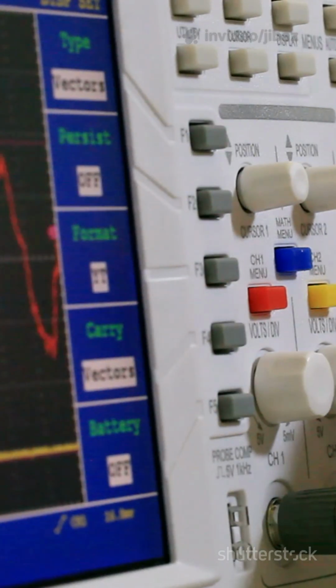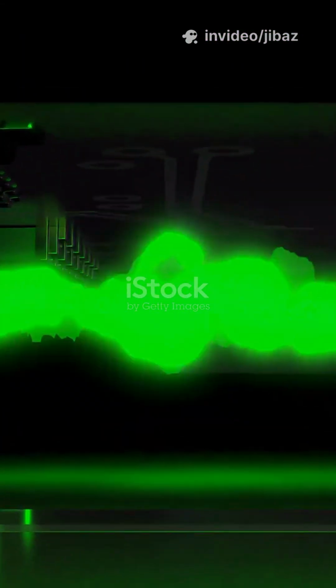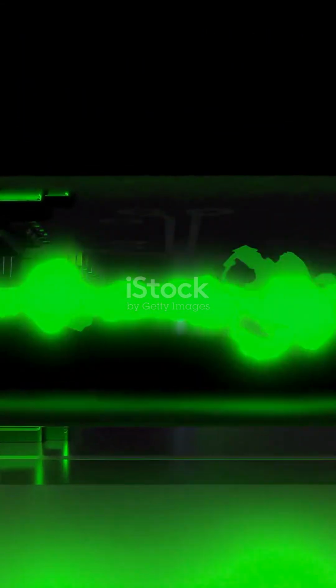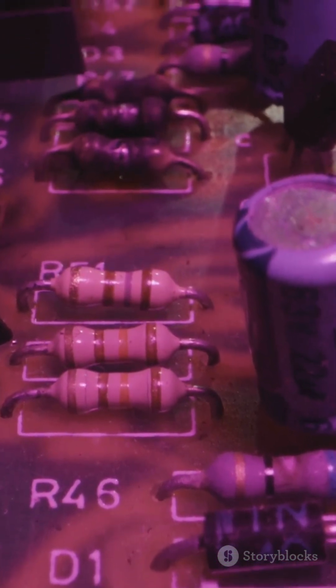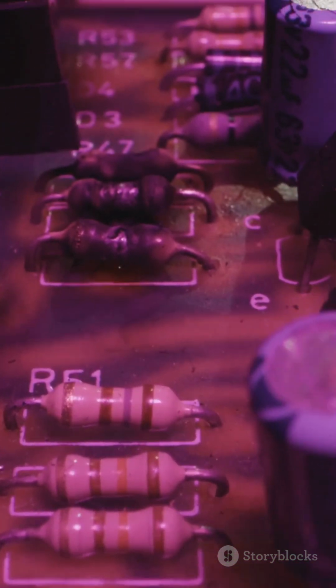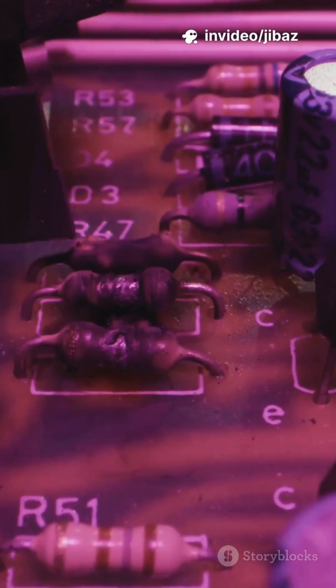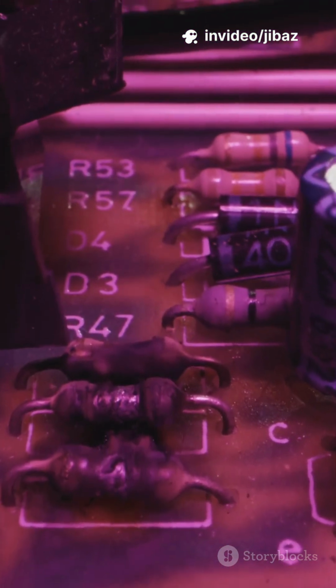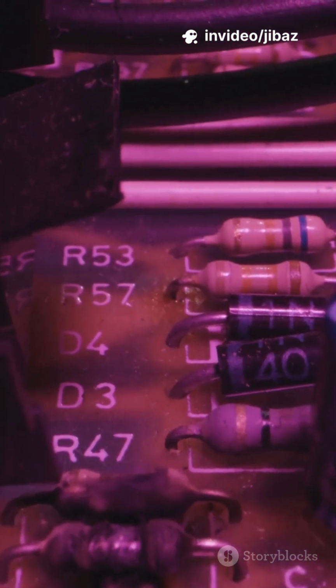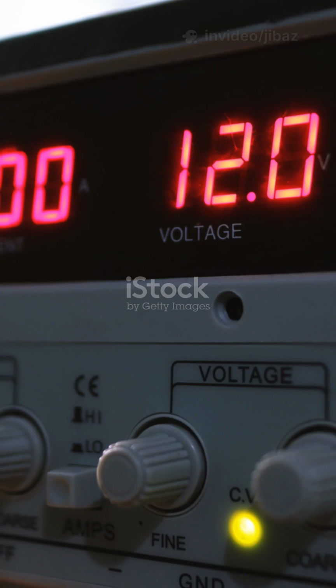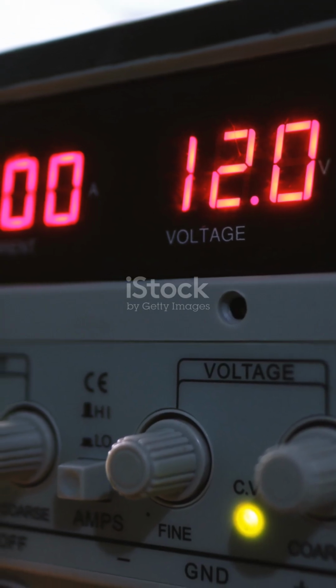Balance is key. An inductor resists changes in current. Placed in series, it smooths out fluctuations. Combine it with a capacitor, that's an LC filter, and you get even better smoothing. It's common in high-power linear supplies. In low-current circuits, RC filters, resistor plus capacitor, are often used to remove small ripples, especially in pre-amplifier power lines or analog stages.